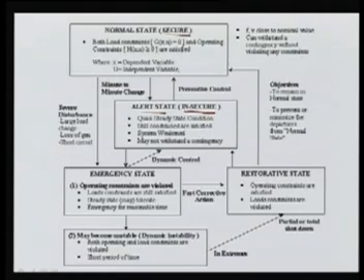In the alert state, it is a quasi steady state condition, and constraints are still satisfied, means both your E and your I are satisfied, but the system is very weak, means if there is any other contingency it may not withstand, and your system may come into the emergency state.